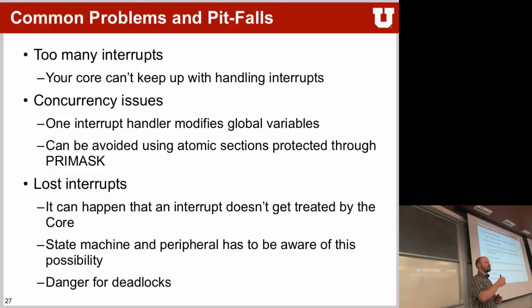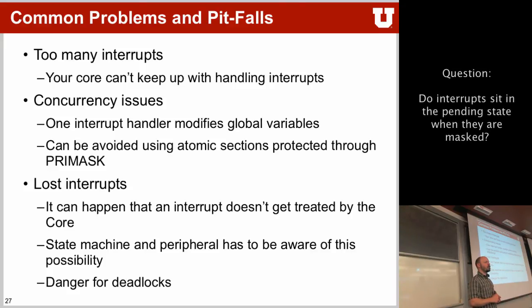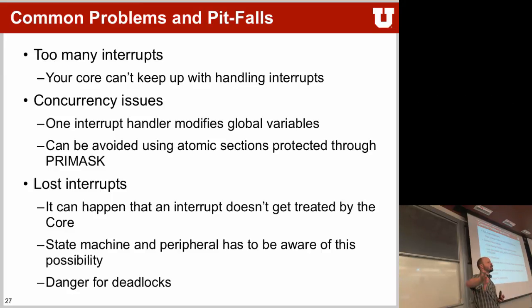Yes? So if you're masking interrupts, do they just sit in the pending state until you say, okay, I'm ready to go back to them? Exactly. They just wait for you until you re-enable them. Because then it looks at which are all pending and it will start executing. You can also lose interrupts.